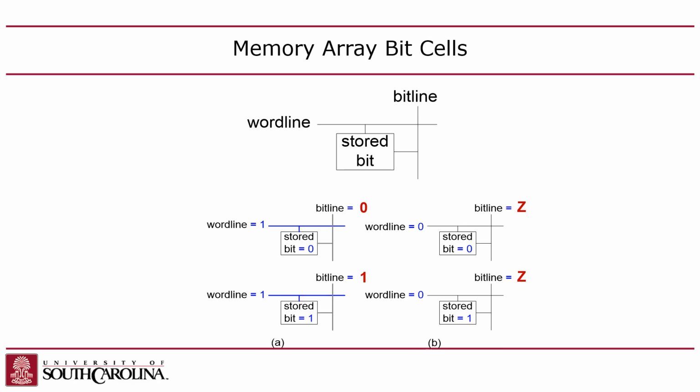So for example, if your memory cell's word line is set, the bit line allows you to write into there, right? So you can write, for instance, a 0 or a 1. Or alternatively, if the bit line is Z, high impedance, then it won't write, right? Now, how do you get Z? We'll use the transmission gate that we talked about earlier, PMOS and NMOS in parallel. You can turn it off and create a high impedance, right? You guys with me?